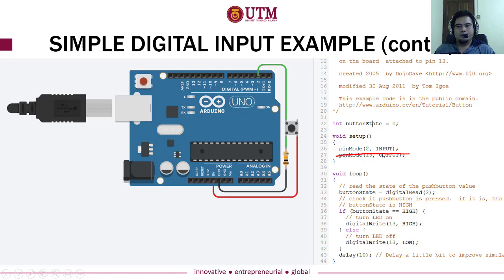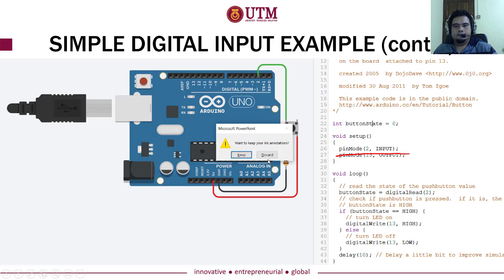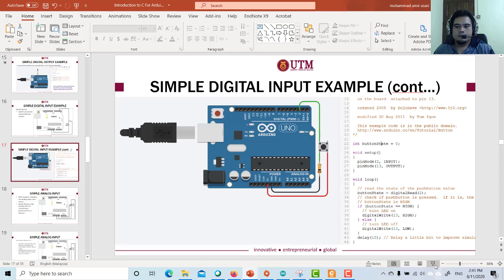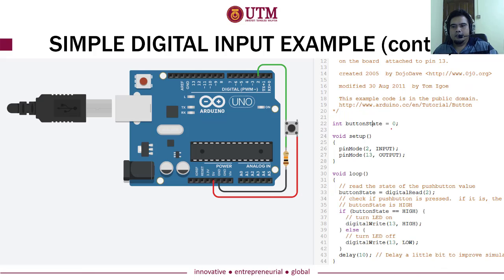So we just play around with our built-in LED, because pin number 13 is our built-in LED here. So meaning that if we set the pin mode 13 as output, then this LED will operate, because now pin number 13 is output.